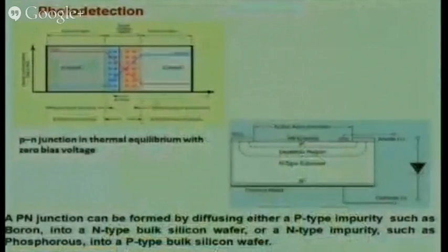So this is what a PN junction is. You have a p-doped material, you have an n-doped material. This is a depletion region. When a photon falls on this depletion layer, it liberates the electron and holes because it has high energy. Once it liberates electron holes, now this can contribute to the current to the outside media, or it can recombine. Either of the two phenomena can take place. We want the maximum output, so that we get the maximum output current.